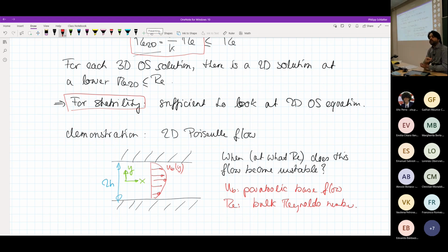So essentially it's the flow rate that I encode with the Reynolds number. And of course then I have another parameter, which is the alpha, because for the eigenvalue I still need to choose my alpha, which is the wavelength in the streamwise direction. So essentially I'm saying, I'm looking at waves that have a specific length, 2 pi divided by alpha. Streamwise wavelength, wave number.